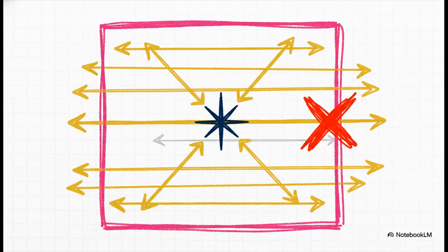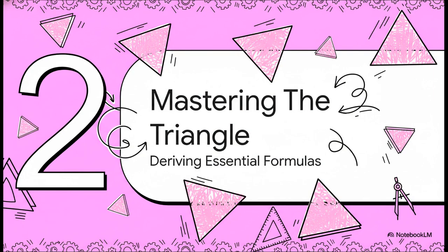Here it is. The single most important thing to remember, the golden rule. The reference axis in the parallel axis theorem, that IG, must always, without exception, be the axis that passes through the centroid. You can only use this theorem to move away from the centroid. You can't use it to move from some other random axis. This is non-negotiable.